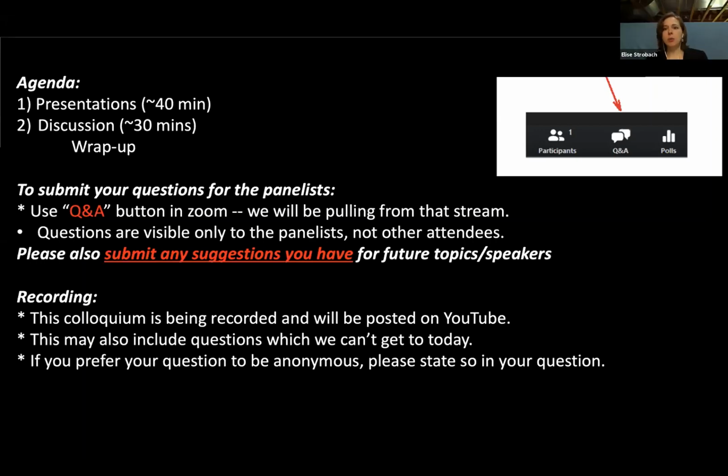So that has been one of the challenges of silica aerogel in particular, this glass-based aerogel, for a really long time. Particularly for transparent applications, as I mentioned, those feature sizes, 8 to 10 nanometers, are really, really small. And you've got a glass material that is only 5% solid. So you've got a combination of a really brittle material, because it's glass and there's not a lot of material there, and a nanostructure that has to remain very small.